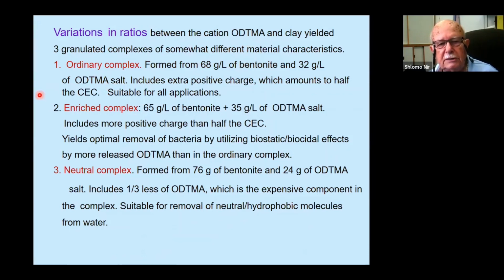And the last slide shows that we had three examples, three ratios between the ODTMA and clay. We had three granulated complexes of somewhat different material characteristics. The ordinary complex, which we always use, then the enriched complex, which is better in removal of bacteria, and then the neutral complex, which showed the same efficiency of removal for hydrophobic molecules such as metolachlor. But it should be recalled that in the case of the neutral complex, there is one third less ODTMA, which is an expensive component in the complex.